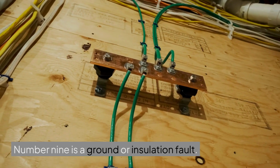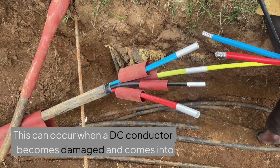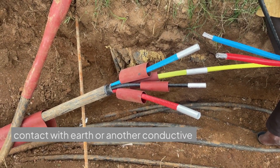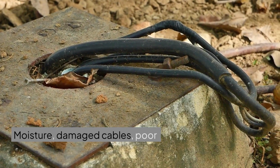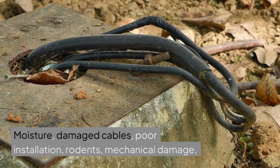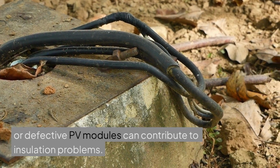9. Ground fault or insulation fault. Number 9 is a ground or insulation fault. This can occur when a DC conductor becomes damaged and comes into contact with earth or another conductive part. Moisture, damaged cables, poor installation, rodents, mechanical damage, or defective PV modules can contribute to insulation problems.